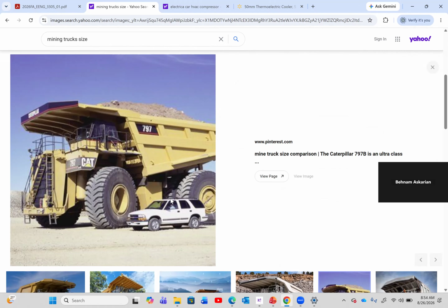For internal combustion, you get that around 2,000-3,000 RPM, or 1,500 RPM for a diesel engine. For an electric motor, you can get it instantaneously from start. It doesn't require any maintenance, so sometimes you just leave it for 20, 30 years. It's cheaper, easier, very quiet, and you have precise control on each wheel. That's the reason they usually have two motors to control each wheel to gain traction when you go up a hill in a mining field.